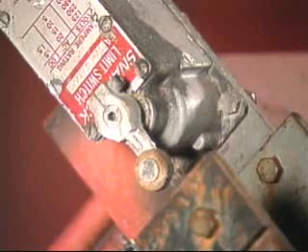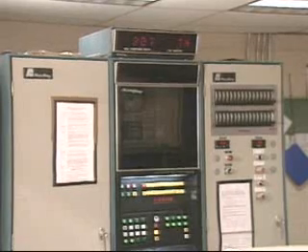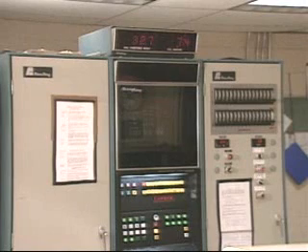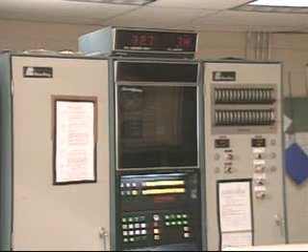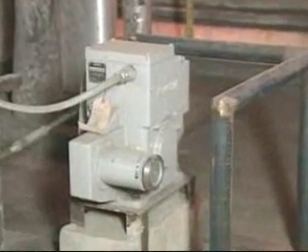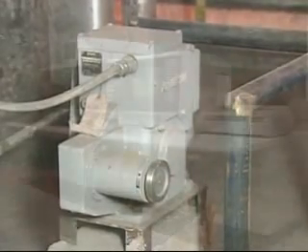Input signals are sent from the process to the computer, which stores their values in memory. Each input value is compared to the appropriate set point value to determine a corresponding output value. The computer uses the output values to generate output signals. These signals are sent directly to control devices that adjust parameters within the process to keep it under control.